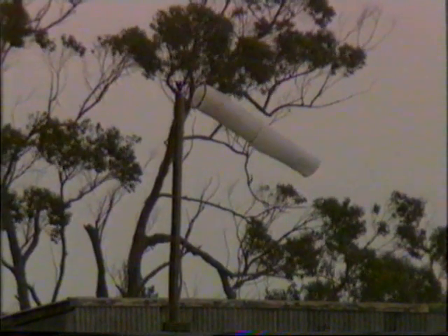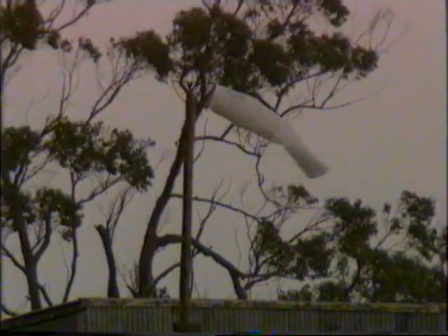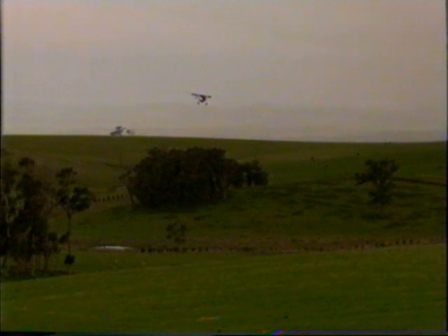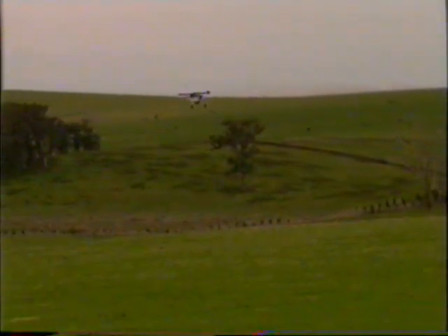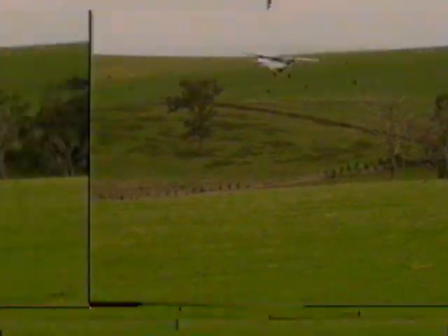Wind shear on approach and landing. As we get closer to the ground, a strong wind gradient causes a decrease in airspeed, an increase in the rate of descent, and it also creates additional turbulence. Power is often needed to control the rate of vertical descent, particularly at maximum landing weights.